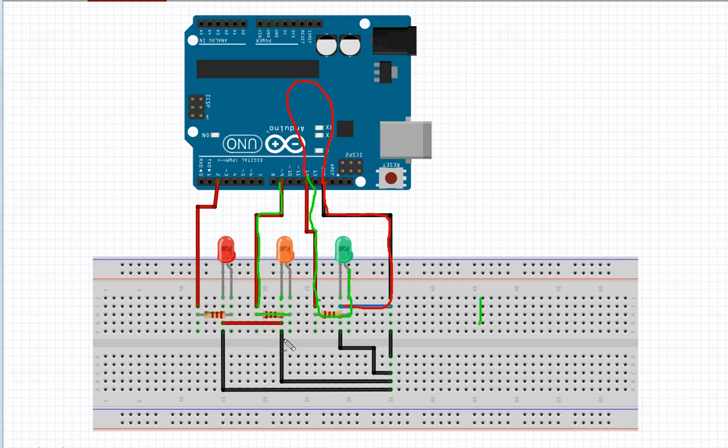And underneath, remember this is one strip, so that's all connected, and this goes in this negative. Remember what I've done: since it's connected, I just put a jump wire there, and all this is negative, and from here it goes into the negative. So I'm sharing the negatives here. Okay, so that's the idea of creating your circuits.